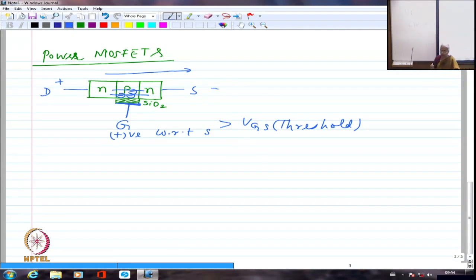So, this is basically a voltage driven device. This is a voltage driven device, and generally the amount of voltage that could be withstood by the gate to source, that junction, is pretty small. It will be anywhere between 12 to 15 volts. That's about it, nothing more than that, which means the voltage what I am applying is also pretty small, nothing much.